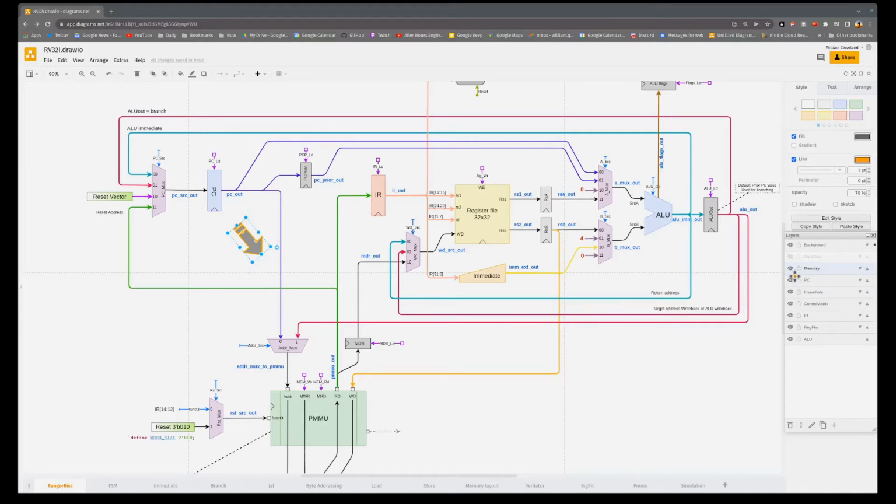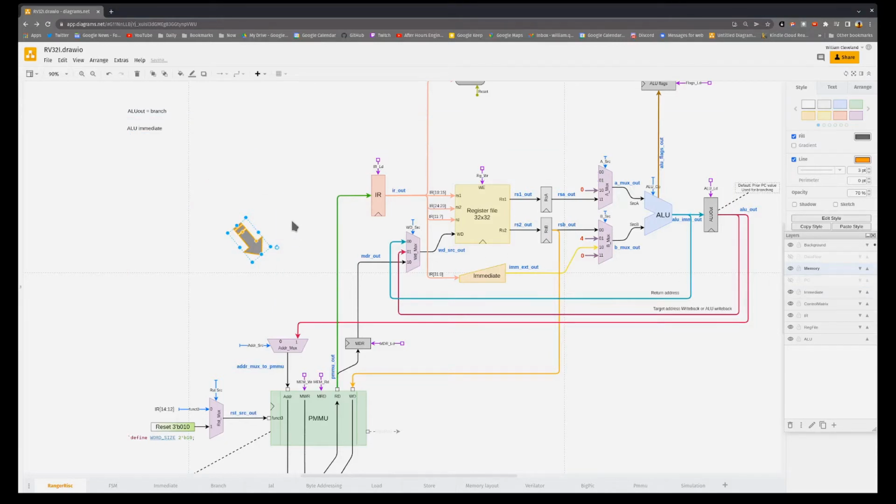So let's turn off the PC, as that's really not relevant to this, and we'll talk about what it is. We have our instruction register has been loaded with a load instruction, and part of it is going to have the destination register to where we're going to load the data, and we're going to pull it from memory. So once the instruction comes in here, it's selecting the destination, but we're also specifying the RS1 as a base register and immediate to add to that RS1. So both of those will route in here.